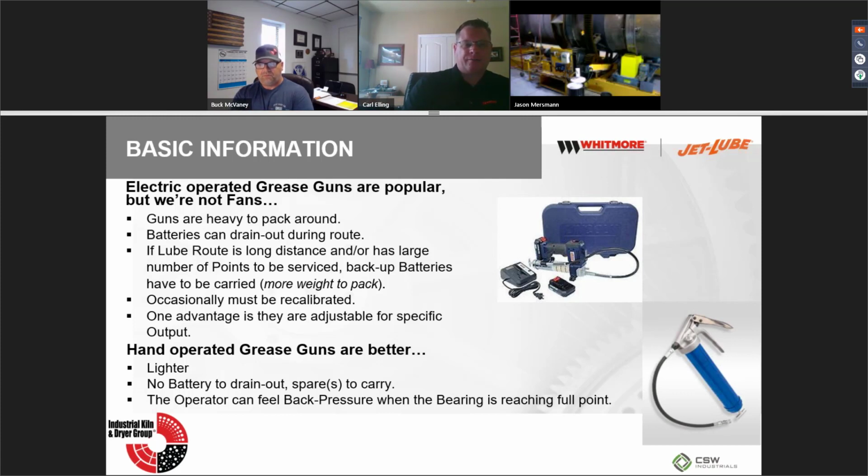So the hand ones, I like them because you can feel the back pressure, and you know when not to put any more grease in there. And they're lighter to carry around. There's no spare parts. There's no extra batteries to carry. So that's one thing. But if you've got several hundred that you're doing in a route, I can see where that would get old really fast. Or, if you need arm strength, that's good. This is a pistol grip version as far as a manual. But there's also the lever version, which I prefer over that one.